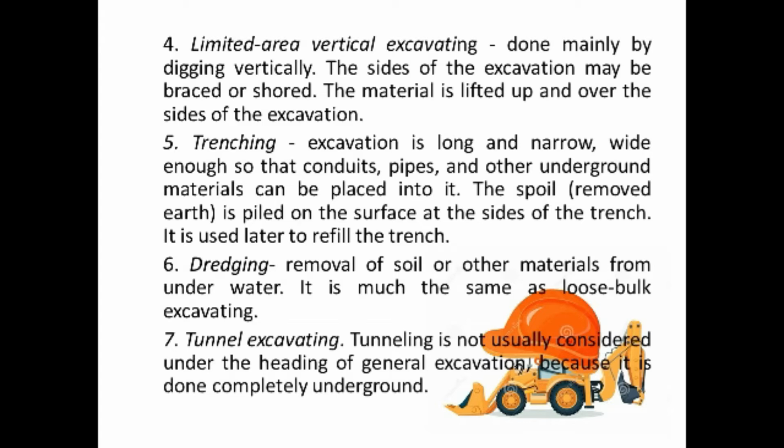Next, we have trenching. This is an excavation which is long and narrow, wide enough so that the conduits or the pipes and other underground materials can be placed into it. The spoil, or the removed earth, is piled up on the surface at the sides of the trench. It is used later to refill the trench.